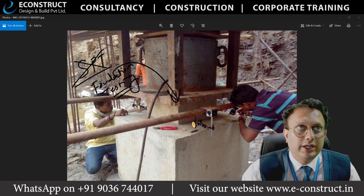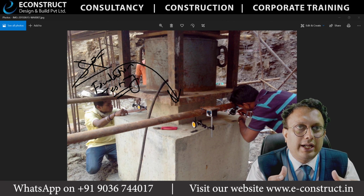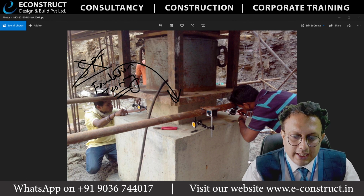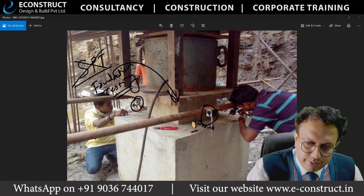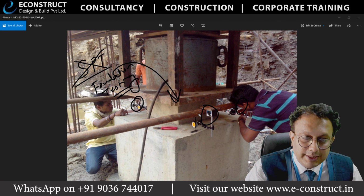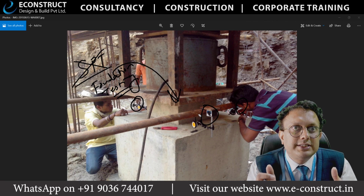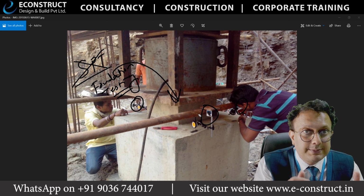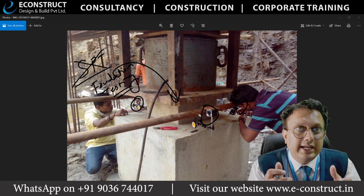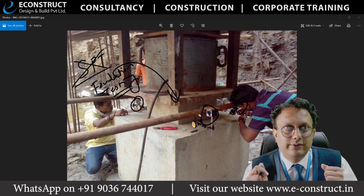What is this actually? This is the real foundation that is going to get utilized on the site, and here you will see the instruments. Different types of instruments will be there. These are basically the gauges showing how much settlement is actually happening on the site. So instead of using the SPT, we would generally insist on using the foundation load test.